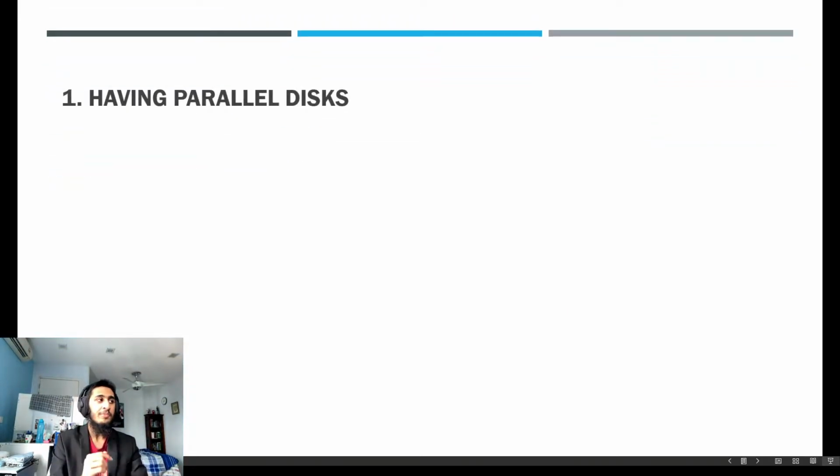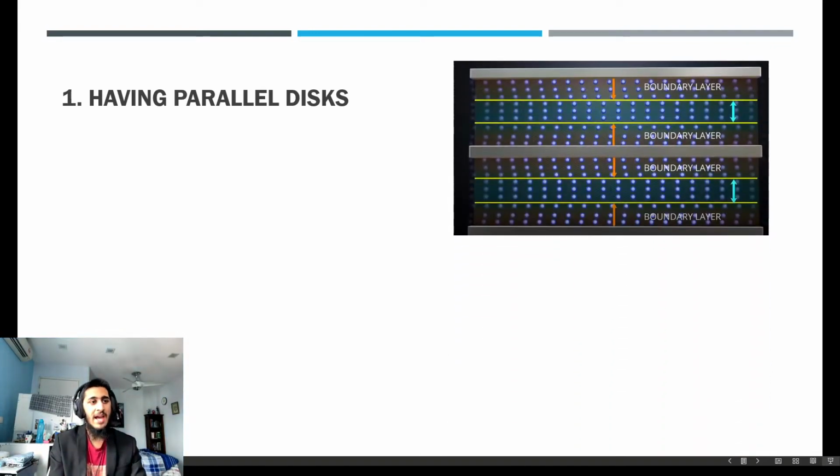Now, let's talk about how steam in particular for the boundary layer applies to the Tesla turbine. Now, what Tesla did was when he saw this effect, he added two parallel plates to that one existing plate, right? And they look something like this image here. They all have boundary layers, but they also have free flow. The thing is, free flow doesn't really contribute much into the system, if anything at all. So a way to make it more efficient would be to completely eliminate that.